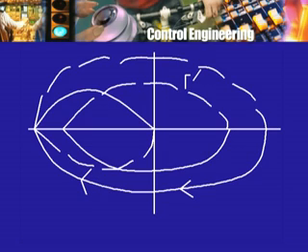And similarly, for the mirror image, the dashed curve will now be like this, and the remaining dashed curve will be like this. The S along the semicircle part still remains very close to the origin, because multiplication by 2 is not going to change it very much. So, now the image contour looks like this, and let me trace it. Starting at low frequencies, I go like this, high frequencies along the semicircle, then low frequencies along the lower part of the j omega axis, and back to here.